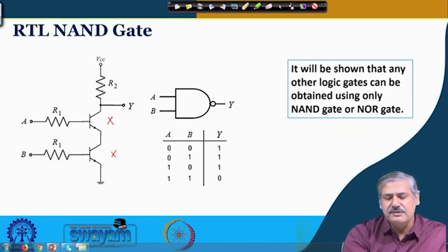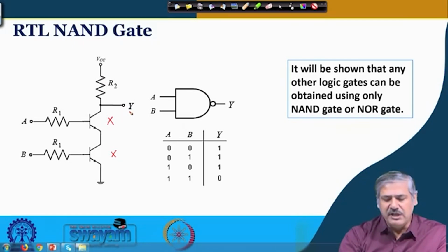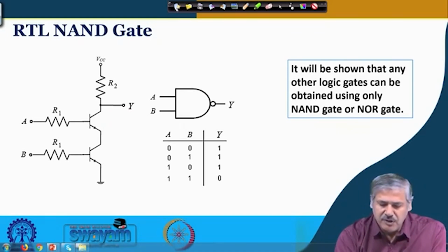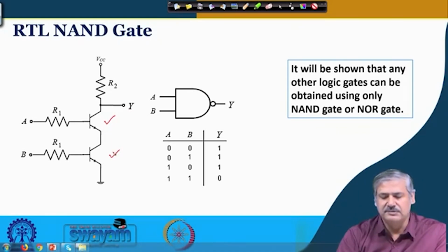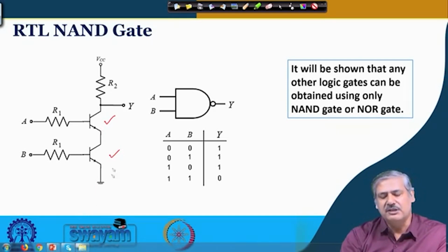Okay. So, this is effectively a high voltage, high condition, and only when both of them are on, okay, a low resistance path to the ground exists. Okay. So, the drop will be 0.2, 0.4 volt or so, right, their saturation, which is still considered as logic low. Is it fine?